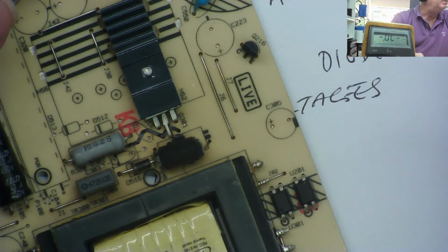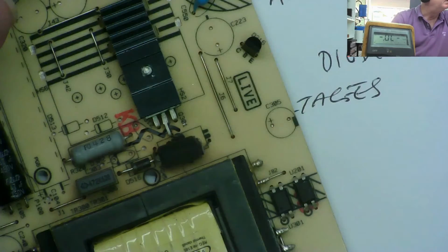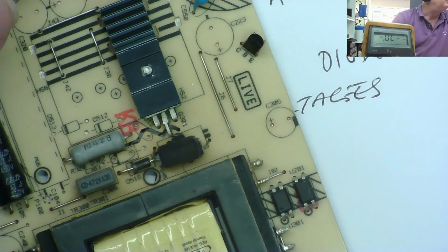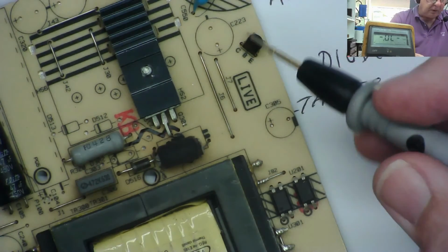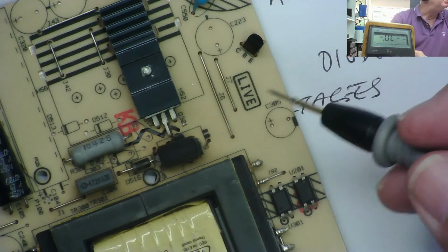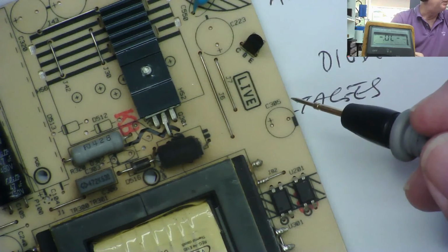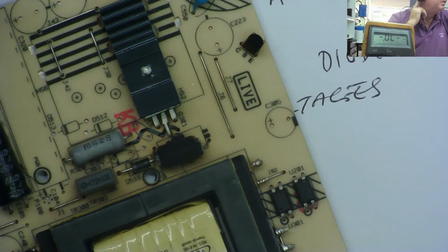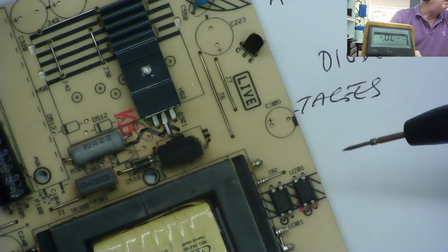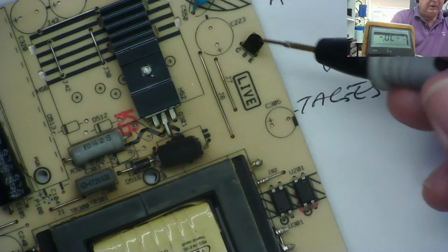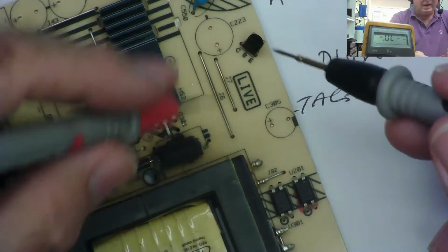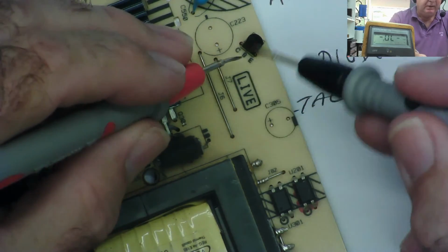In the old days it used to be T or TR. These days it seems to be Q. So depending if you work on vintage stuff, it might be different. Also, just because it says TR doesn't mean it's necessarily a bipolar transistor. It could be a MOSFET, yeah? Or if it says Q, it could be a MOSFET. Everything that's on three legs isn't always a transistor, yeah? On surface mount you can find diodes that have three legs, but they only use two of them. So this is our transistor.